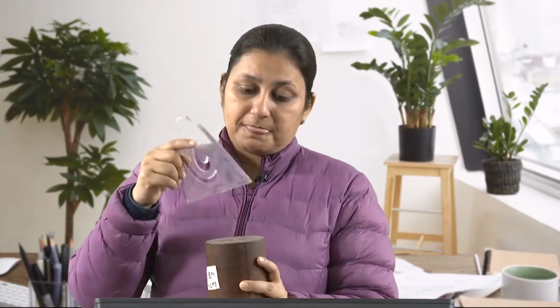There are two important things. One, how the solid is being cut through the section plane, that is, the relative position of the section plane and the solid. The section plane may be perpendicular, inclined, or horizontal. How is the section plane being kept in relation to the solid? That is the first thing. The second thing is: from where are we viewing the section which is cut? If we are viewing it from the side, from the top, from the front, where are we viewing it from? That will determine how the object looks, and that is equally important.